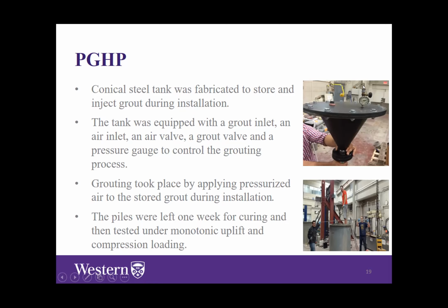An air inlet here applies air pressure to the stored grout so that we inject the grout under high pressure, which will improve the grout bond.